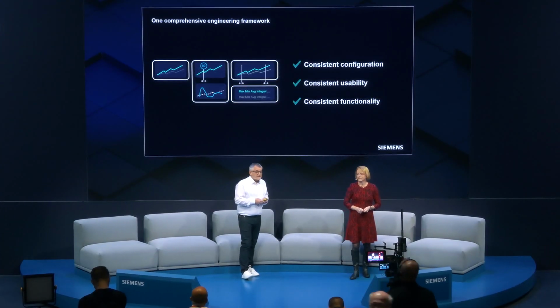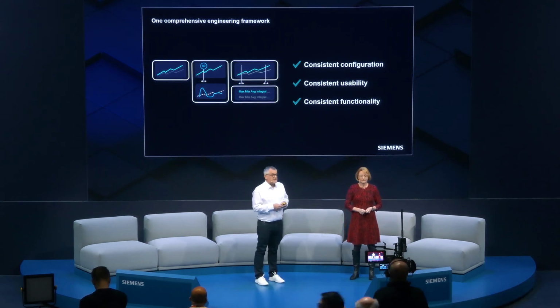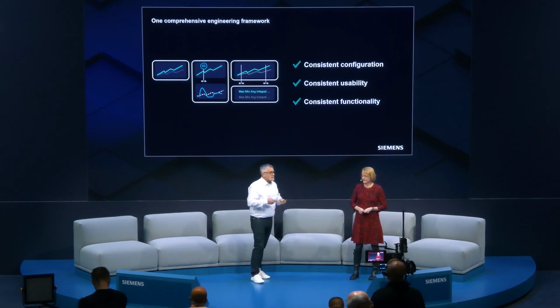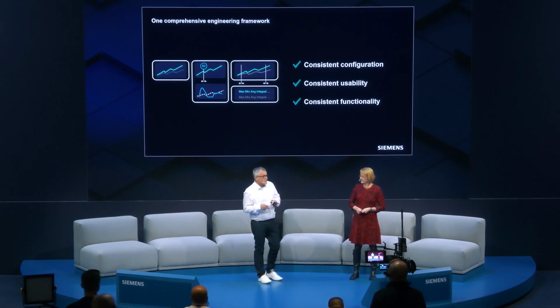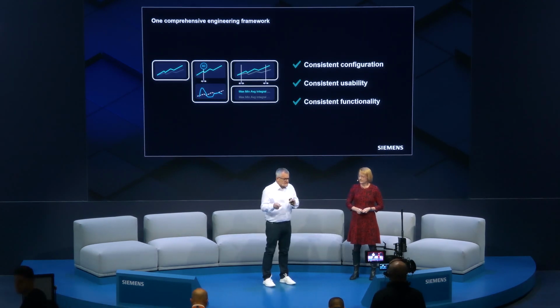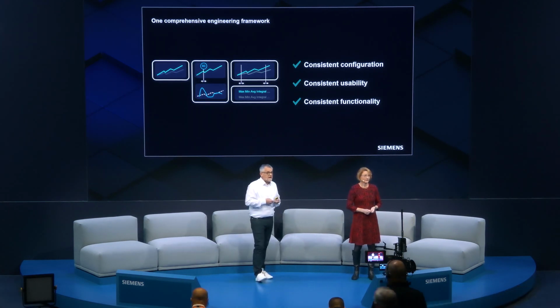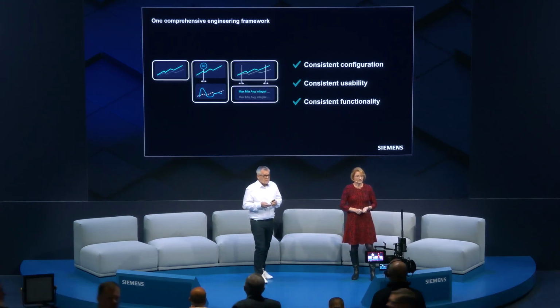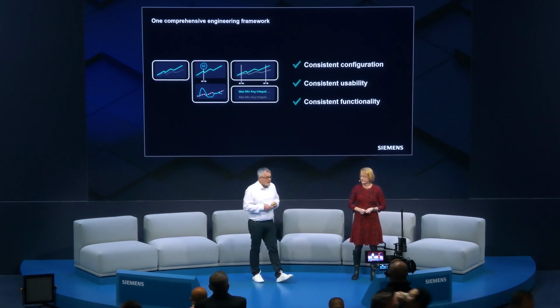Moreover, WinCC Unified offers one comprehensive engineering workflow. What's the meaning of comprehensive here? Just an example: you don't only have one trend curve on an HMI, you can arrange multiple trends in one control. You can select different ranges to be displayed, or you can perform and show online statistics and analytics such as average, minimum, and maximum values on trend curves. Or a top 10 analysis on alarm controls, the so-called hit list. And this is without additional scripting, on PC and on the panel.